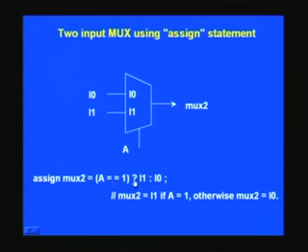And the question mark is once again a mandatory thing, and for the mux this structure at once reveals that it is a mux implementation, and it has 2 inputs as we have already seen. The first input that you write is not I0, please make a note of this. We will have to write I1 first, followed by a colon which separates this input from the other input. This is clear, I hope.